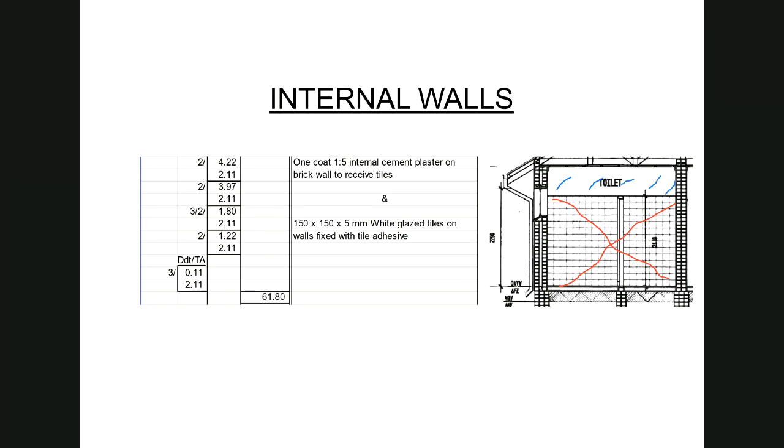So now I need to take my overall dimension of 2.79 and split it between 210 and what is above the wall over here. I'm dealing first of all with the plaster underneath the tiling area over there. So let's look at the description. I'm saying 1 coat of plaster.